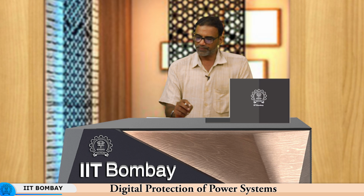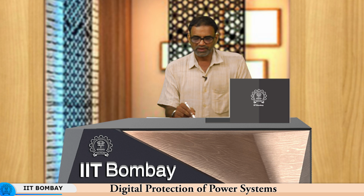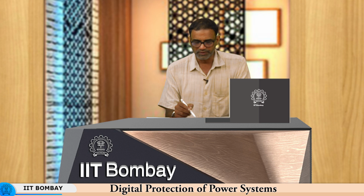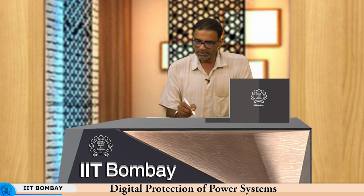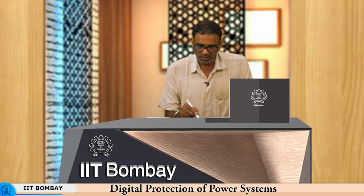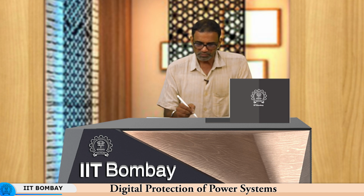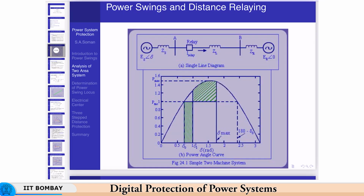Okay. So, now what happens when there is a fault? Okay, this is a single line here. So, when there is a fault on that line, we are assuming a solid fault. So, there is no power transfer possible, and the power transfer goes to 0. Initially, as you can see on the P versus delta curve here, the x axis is delta, the y axis is P, and initially it is operating at this point here, the red dot that I have shown.